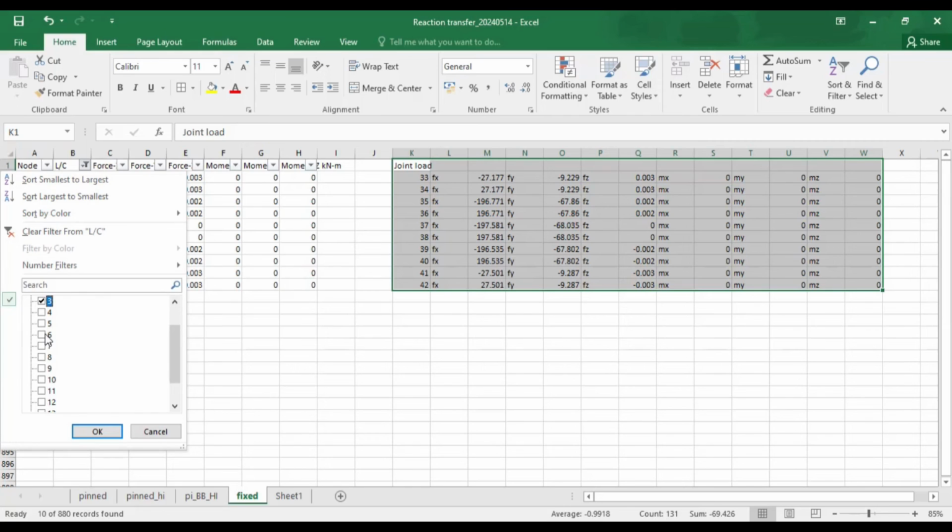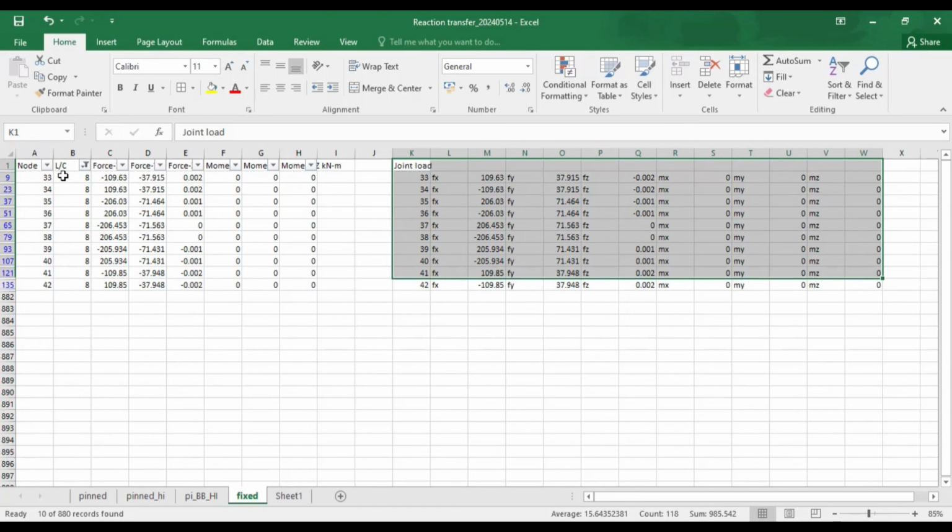That's why I have considered only basic load cases, because see, rest of the things will be taken care of by the load combinations only, right? So once you enter all the load values for your basic load cases, automatically load combinations will take care of those values, right?